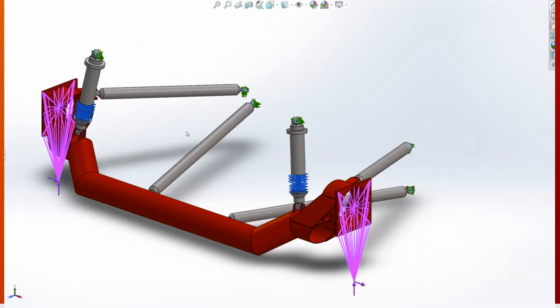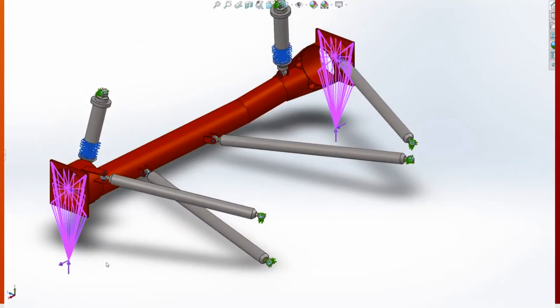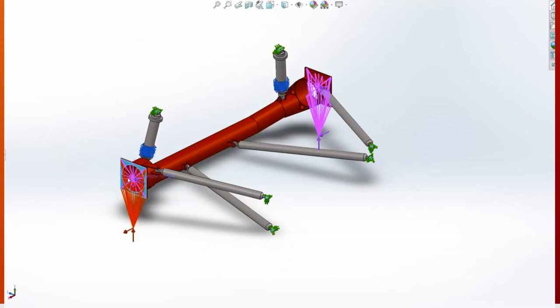The pink lines move to where the contact patch is, as well as the direction of the forces, although it does not tell you the magnitude. It's just a unit vector of 1. So realize that the lateral force you see there, X, is 450 pounds, and the normal, I believe, was 200. Oh, correction. Lateral force of 450 pounds at the contact patch, and also 350 pounds of normal force. That is why the Y is negative 9 inches, because it is acting at that contact patch. And what we're most worried about is the moment caused by that.